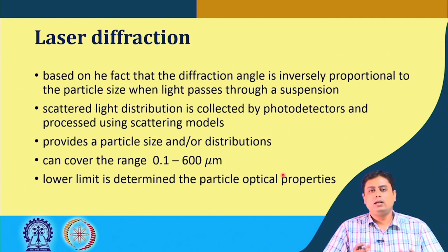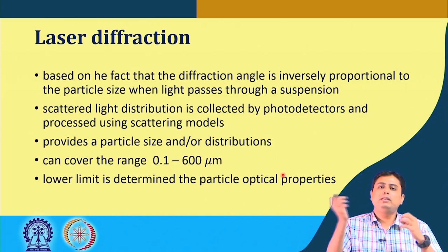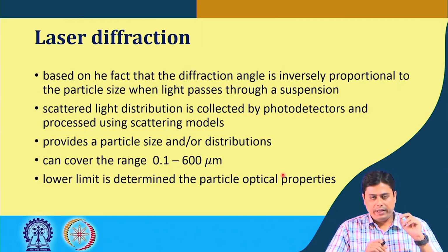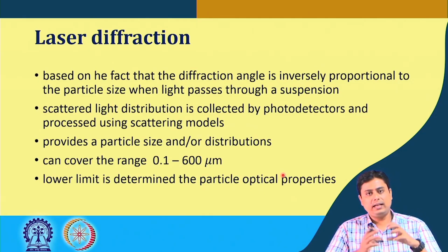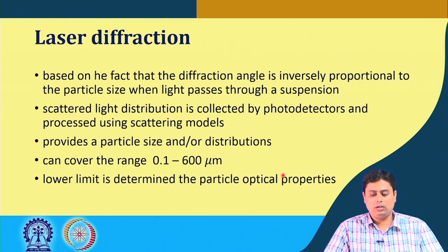So, if you have particles suspended in a fluid media and you throw a laser light, the light will be scattered when it is incident on a particular particle. All these scattered lights are then collected and processed in a photodetector, and there are several scattering models available to process those signals. Then it provides the particle size and its distribution.